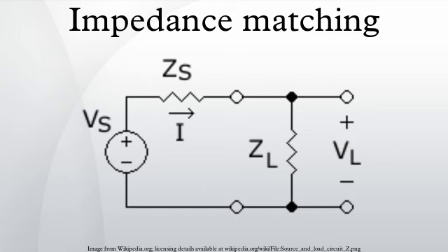Reflection-less matching: impedance matching to minimize reflections is achieved by making the load impedance equal to the source impedance. If the source impedance, load impedance and transmission line characteristic impedance are purely resistive, then reflection-less matching is the same as maximum power transfer matching. Complex conjugate matching: complex conjugate matching is used when maximum power transfer is required. ZL = ZS*. This is different from reflection-less matching only when the source or load have a reactive component. Where * indicates the complex conjugate.